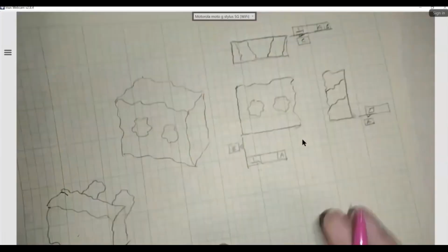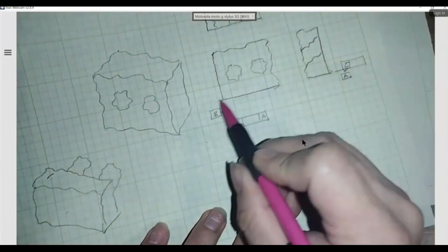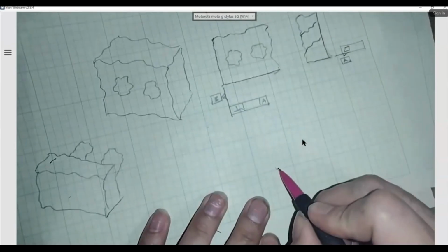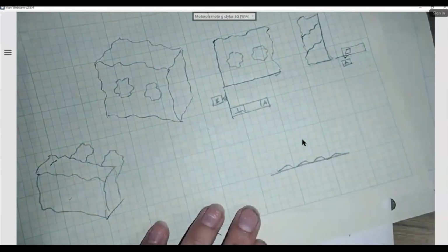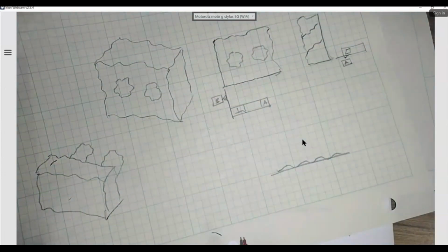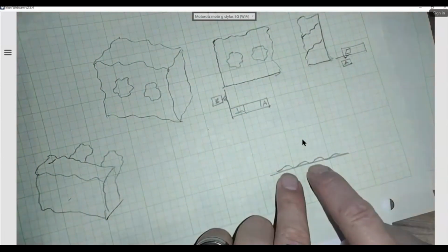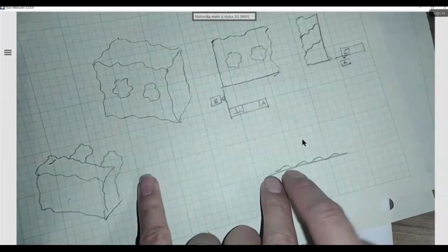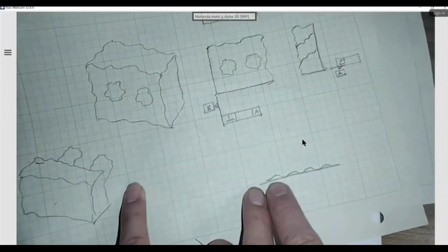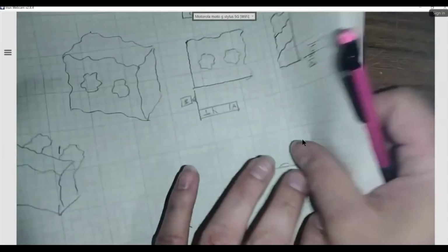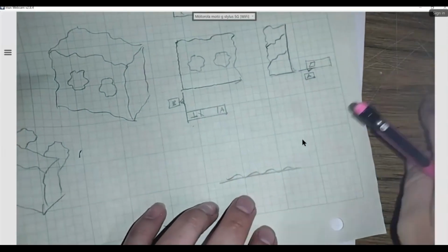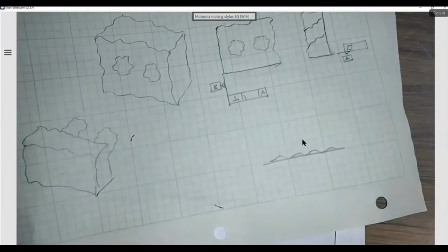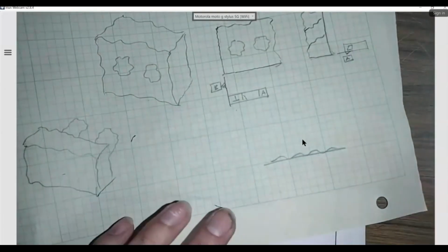Also, I need to consider that even when I have taken care of the surface, my surface is not perfect. My surface might still be wiggly. That makes sense? So I am going to measure when it actually gets to be produced or inspected. I'm not going to be measuring from my imperfect part. I'm going to be dimensioning from either a granite table or a milling table, or maybe a lathe that will hold the part and will rotate, right? Much better than my part.